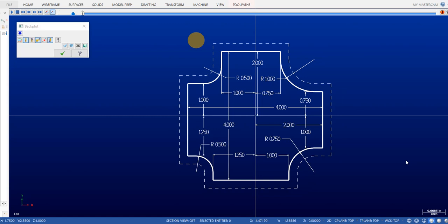Alright, so now let's take a look at the toolpath with a perpendicular move to activate cutter comp. All it's going to do is make a 0.100 perpendicular move right there, and on that line of code, when we post that out, we're going to add a left cutter compensation code. In this case it will be a G41, and that allows us to make minor changes to the dimensions of the part by adding an offset in the tool offset page,